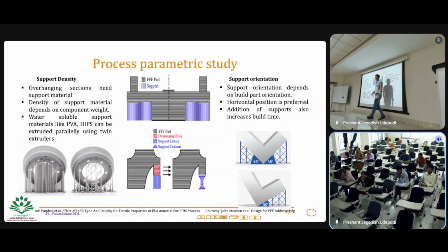Where you can extend your layers. For example, think about you have one layer like this, right? So another layer, if you want to extend without support structure, you can build something like this, right? So now you are taking advantage of a previous layer, then you are laying other material, so that you can see how much angle you can go without support structure, right?